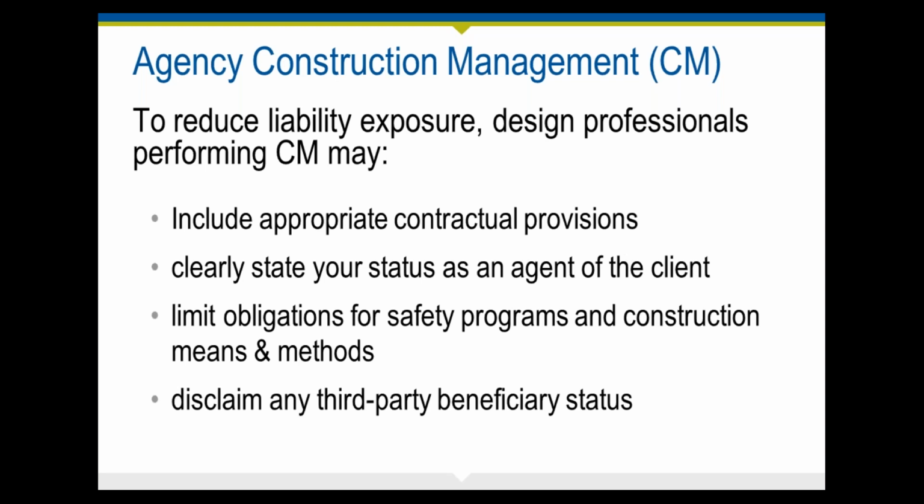If you are the construction manager acting in the agency position, you should only owe the client a duty on schedule and cost issues, not the contractor or anybody else, right? You should also disclaim any third-party beneficiary status related to the construction manager's performance and obligations, and allocate risk to the contractor and its subcontractors for claims relating to safety and construction means and methods.